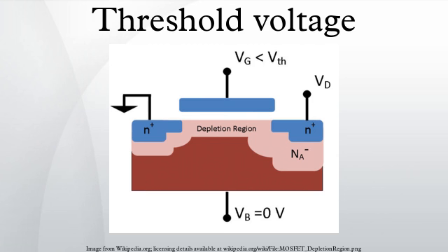If the gate voltage is below the threshold voltage, the transistor is turned off and ideally there is no current from the drain to the source of the transistor. In fact, there is a current even for gate biases below the threshold voltage, although it is small and varies exponentially with gate bias.